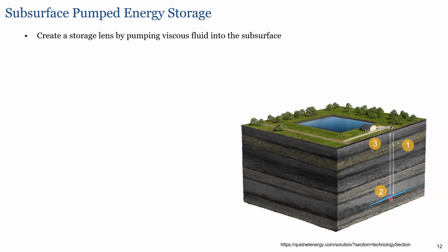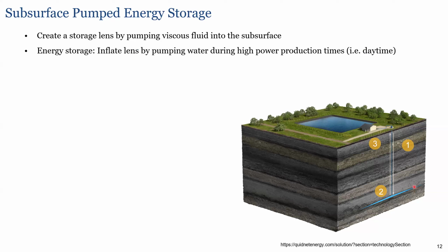And what is a lens? It's a hydraulic fracture that's no longer growing. So this lens is created in such a way maybe that there's some material that is packed into the tip so that the fracture tip doesn't see the pressure anymore and it stops growing. So that from that point, it can be inflated and allowed to deflate, its storage being a capacity for energy storage.